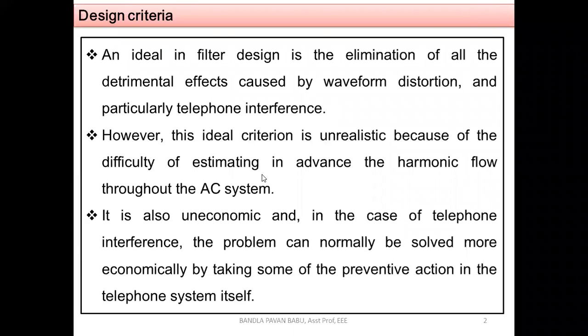So as per the statement, we can say that just by placing a filter we can reduce the harmonics, but that is not the case. Before placing the filter, we need to analyze the order of the harmonics, the frequency level, and the magnitude. For that particular frequency, how can we eliminate those particular harmonics? So before placing a filter, we need to analyze the actual representation of those harmonics.